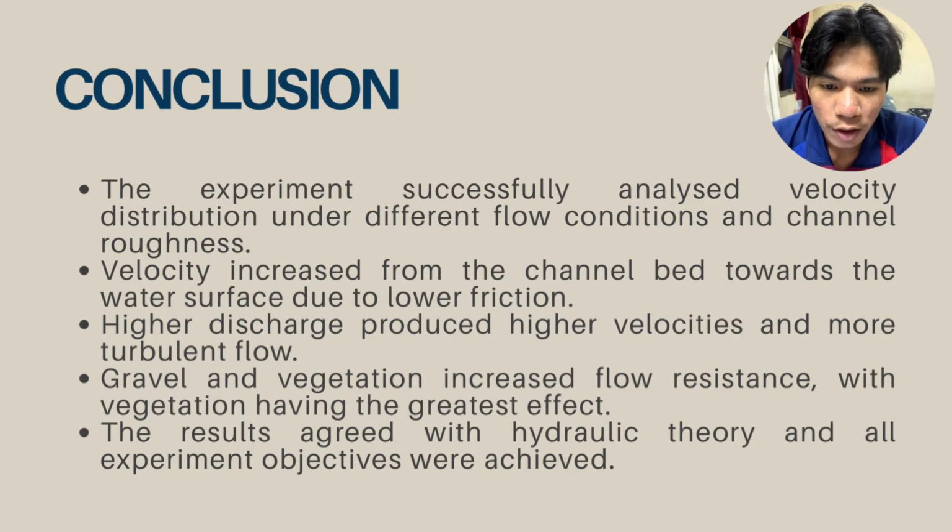Finally, I will conclude our experiment and present a few recommendations. From this experiment, we successfully analyzed the velocity distribution in an open channel under different flow conditions and channel roughness. The result shows that the water velocity increased from the channel bed towards the free surface because the friction is lower near the surface. We also found that a higher discharge produced higher velocities and more turbulent flow.